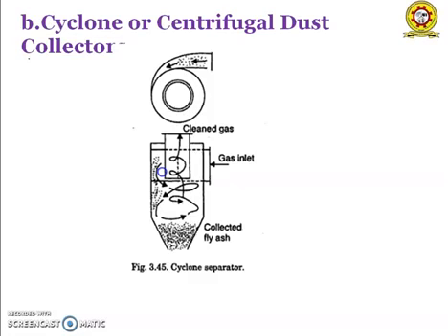The factors which affect the performance of this collector are gas volume, particulate loading, inlet velocity, temperature, diameter to height ratio of the cyclone, and dust particles.